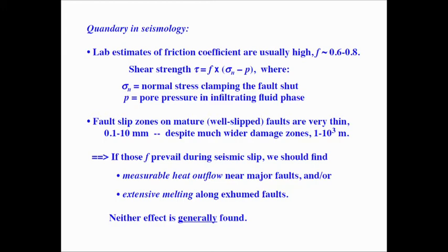And I'll remind you that the static friction coefficient enters in an expression for the shear strength of a contact, like the surface of a fault. The shear strength is the friction coefficient times what's called the effective normal stress, the total stress clamping the fault shut, minus the pressure in any infiltrating pore fluid.